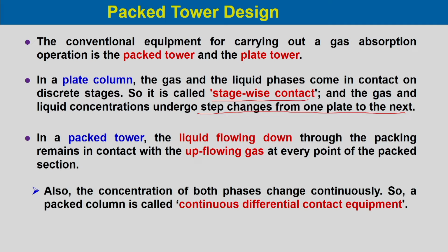So, at every stage of the column there is intimate contact between gas and liquid. That is why this type of packed column is called continuous differential contact equipment. So, there is no step change. At every point there is a change of concentration as the gas flows from bottom to top or the liquid flows from top to bottom.